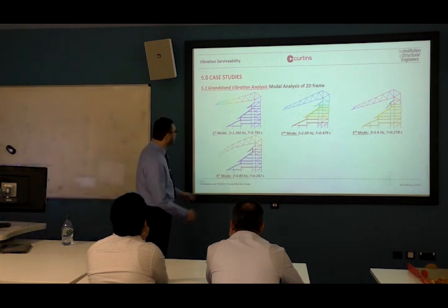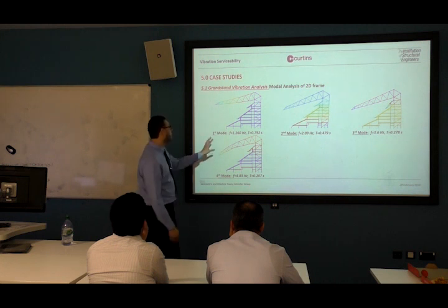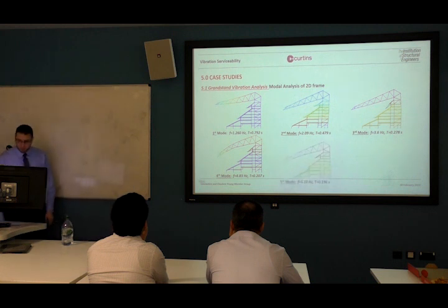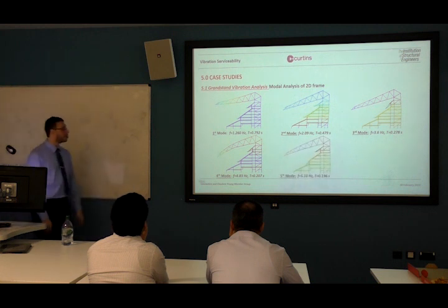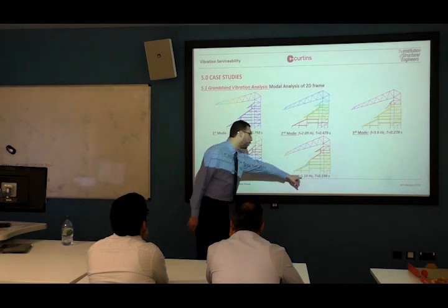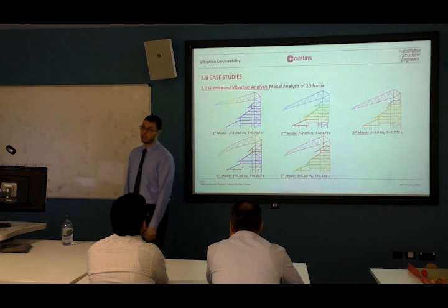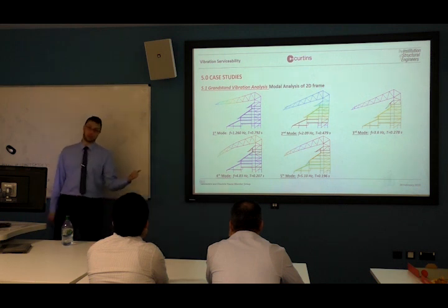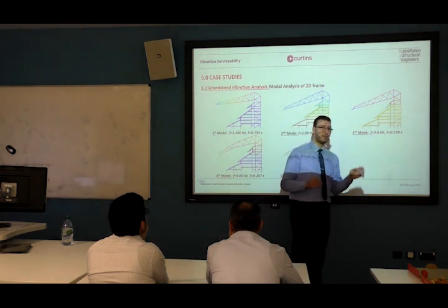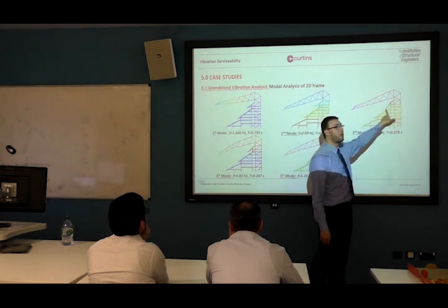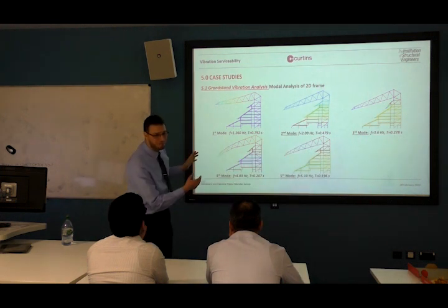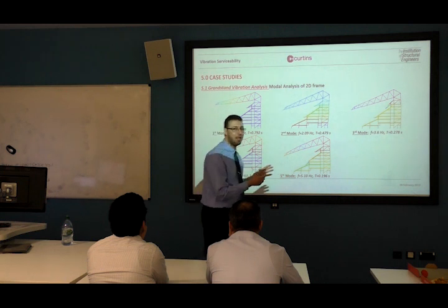The fourth mode is another shape of the roof deflection. The fifth mode is the second raker moving as well, which is also less than 6 Hz. I've checked that one, and that's pretty stiff. Just to give you some idea, this one is about a 9 meter cantilever. It looks small here, but it's about 9 meters.